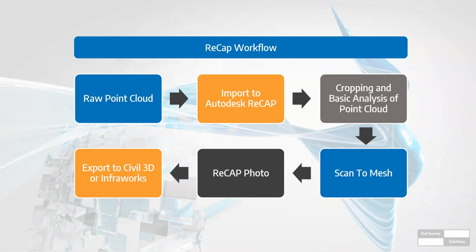You then run scan to mesh. Depending on the size of your point cloud, I would recommend doing this overnight, as the one that I showed earlier took me about an hour to scan to mesh, upload it, and get it ready for Recap Photo.